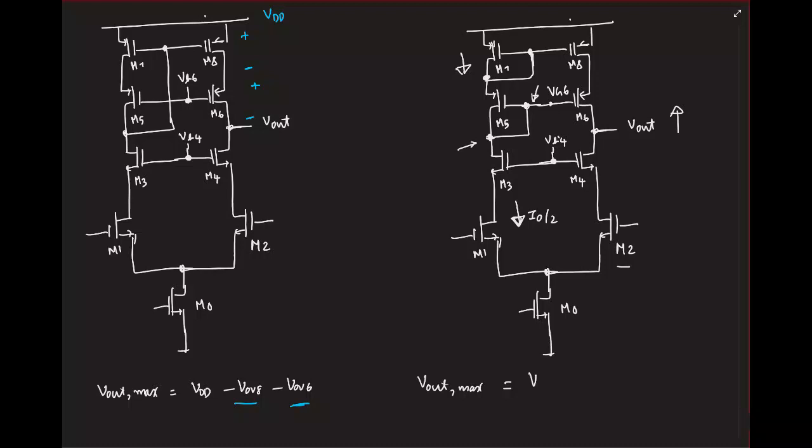It's not a complicated question. I'm just saying we have a PMOS transistor, gate voltage is at VG6. What is the maximum drain voltage for the PMOS transistor? One threshold higher than its gate. Okay, so this is VG6. And what is VG6? What is fixing VG6? Yeah, so if you think about it, we have a source to gate drop here, right? So if I call this VG8, what is VG8?